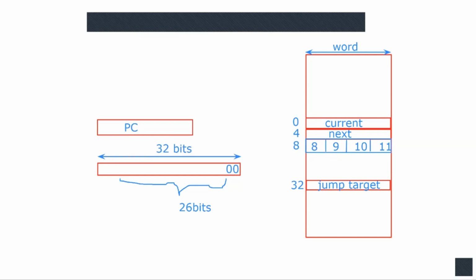The program counter stores a 32-bit address. But since the program counter is used to access this instruction memory and it accesses instruction words, not instruction bytes, we don't really care about accessing these 4 different individual bytes in an instruction word. So we don't really care what the 2 least significant bits are, right?